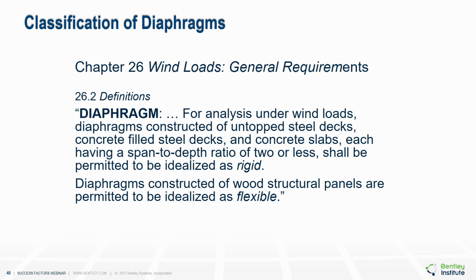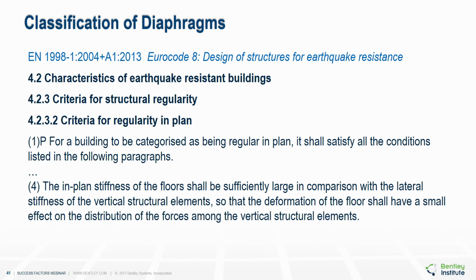Most notably, whereas for seismic analysis, untopped steel decks may qualify as flexible diaphragms, for wind analysis, they may qualify as rigid diaphragms. And so for wind analysis, most diaphragms will qualify as rigid. Let us now turn our attention to the Eurocode.